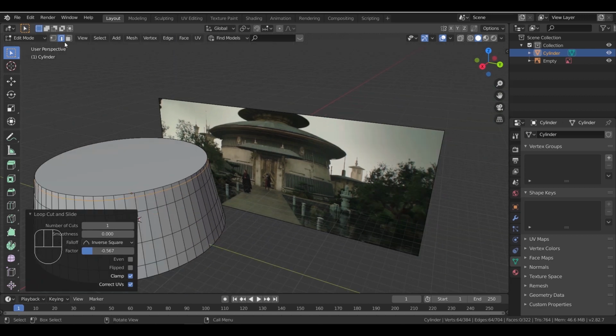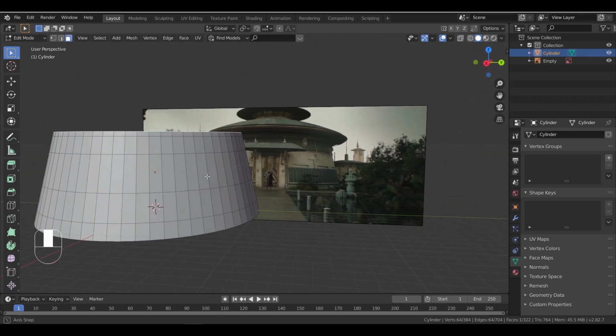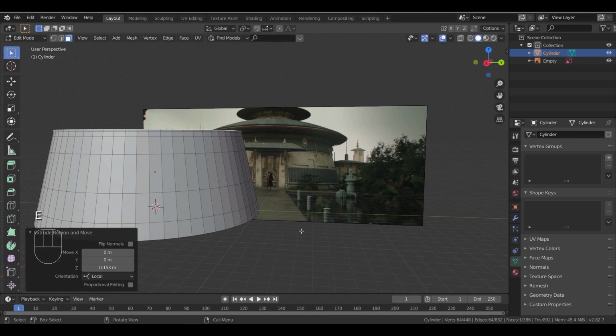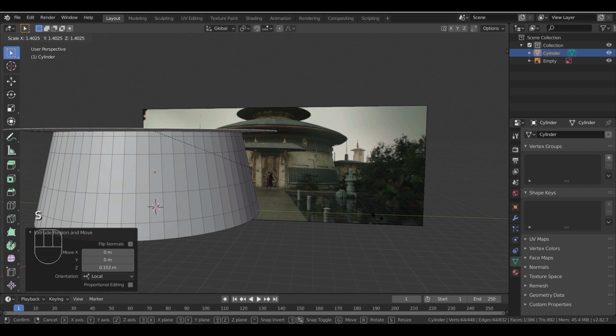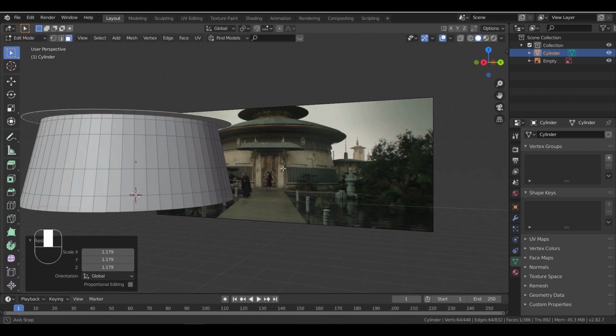Once you added those cuts, let us finish the top part. This area here is of 4 steps, and I will use extrude and scale commands to give it the basic shape, and later on we will add some smoothness to it with bevel.